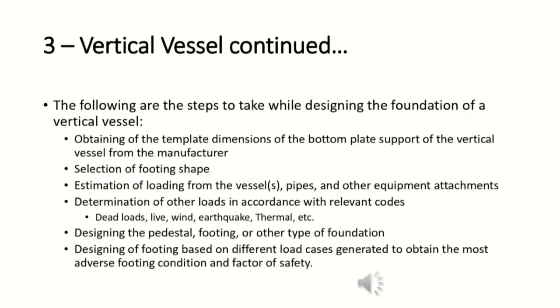The following are the steps to take while designing the foundation of a vertical vessel. 1. Obtaining of the template dimensions of the bottom plate support of the vertical vessel from the manufacturer. 2. Selection of footing shape. 3. Estimation of loading from the vessels, pipes and other equipment attached. 4. Determination of other loads in accordance with relevant codes.